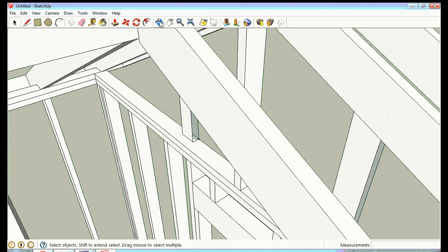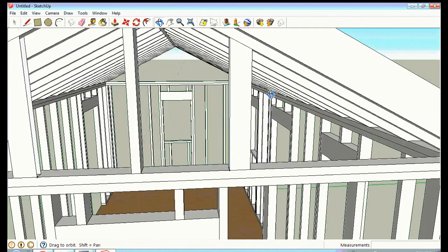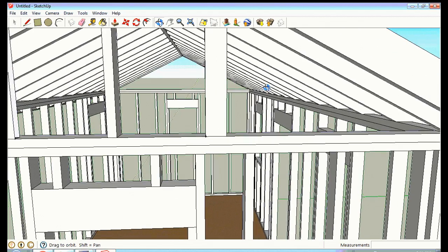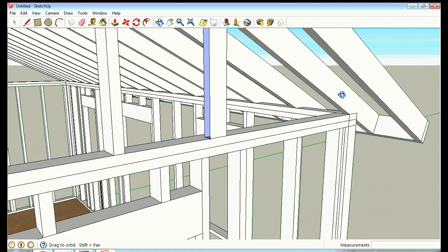Okay, that gives me my supports for my end wall. And I would put in another support over here. You see that you've got this face here. So you're going to cut a piece of plywood that fits in and goes against this, underneath this edge, all the way up to your roofing material.